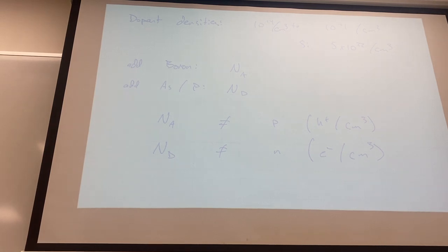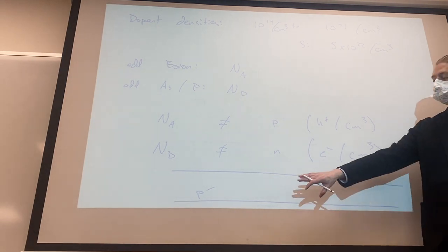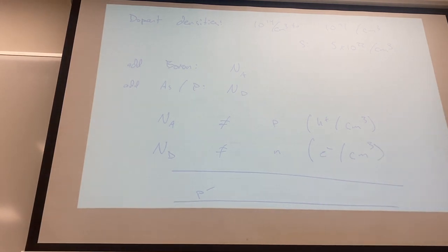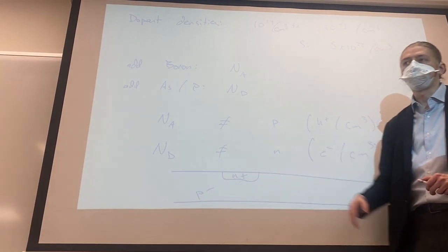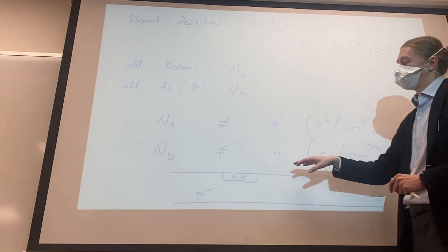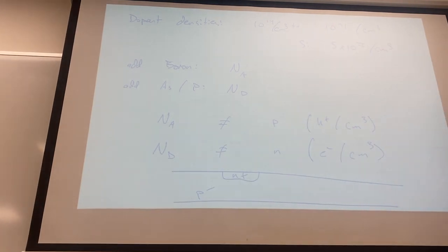Or what happens frequently is you start with a chunk of silicon and you lightly dope it with just a little bit of p-type material. And we tend to annotate that by saying p minus or p plus or p plus plus to say relatively if this is a little bit or a middle amount or a lot or a whole lot. It's common to have a silicon wafer that is uniformly p minus a little bit. And then if you want to turn that into an n-type device, you diffuse some n into that, but it's dealing with having a little bit of p-type material in there already. So that's going to subtract from the efficacy of all the donor material that you're adding in.